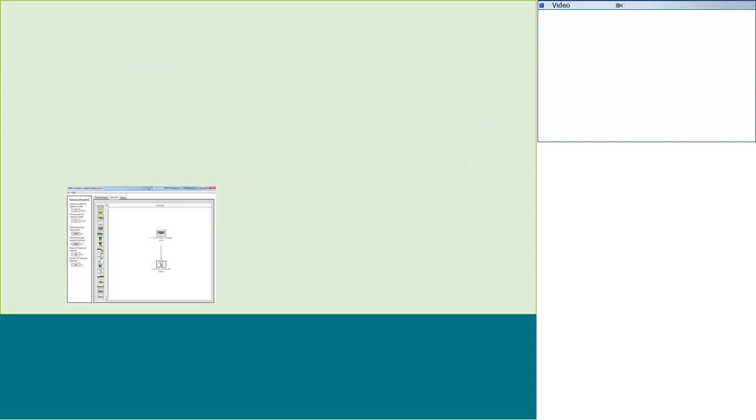So when you're in the manual, in the calculator, keep thinking manual here. If you're in the calculator, this is the reuse icon down here. I have a pond system set up here. For those of you who have pond systems, don't forget to put your pond in and route the water from the pond to your reuse system, because that's going to give you extra phosphorus and TSS treatment. That's not an option in a storage tank unless you're a really savvy and creative modeler and want to come up with something imaginative, but I'm not trying to encourage anybody to do that.